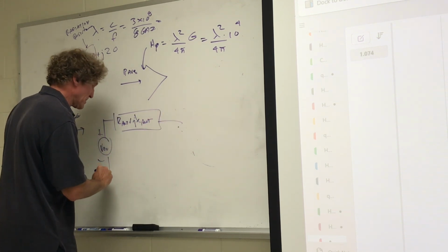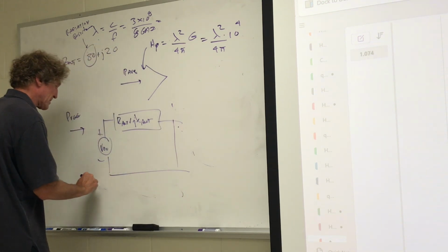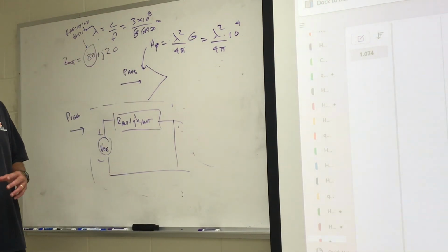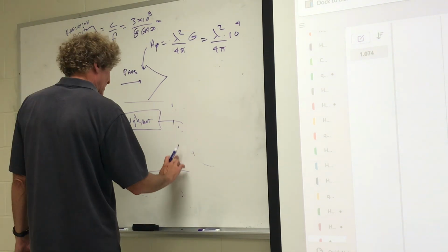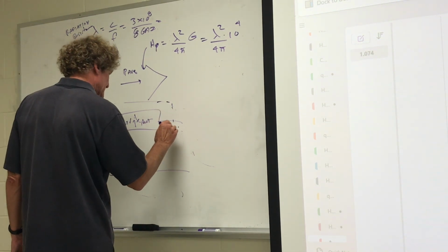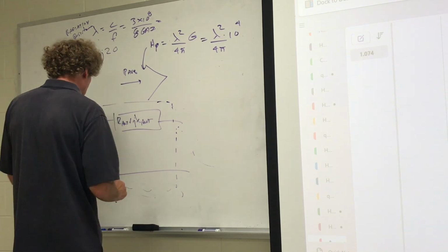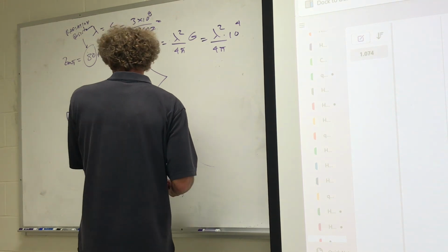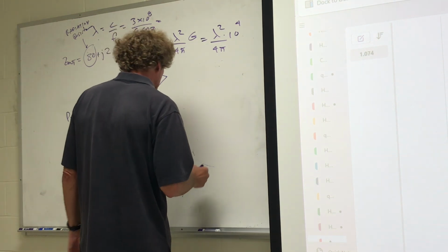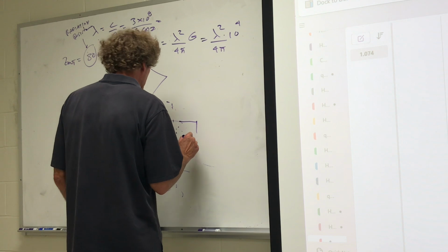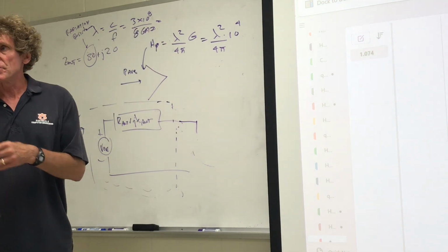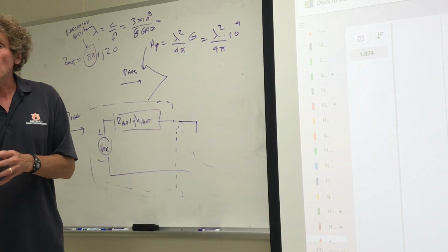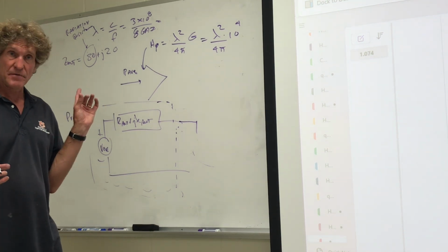Now that's all internal to the actual antenna, right? Remember, we're trying to get an equivalent circuit for the antenna. This is external. Now I can say that this is basically all internal. This is the antenna itself. It's got some open circuit voltage in series. It's a Thevenin equivalent with some impedance. Now you got a load. Well, the maximum amount of power you can get out of this system is when the load itself is the conjugate of the antenna impedance.